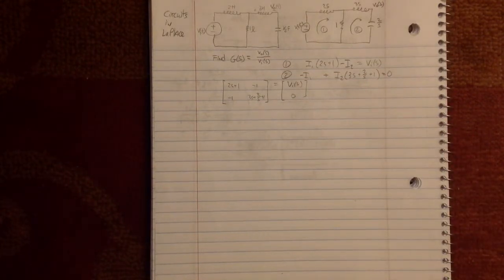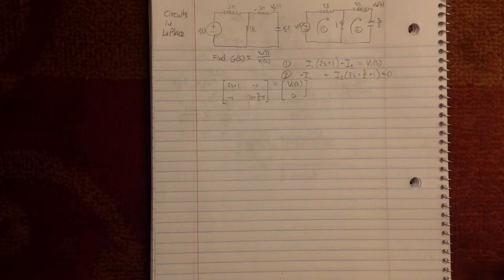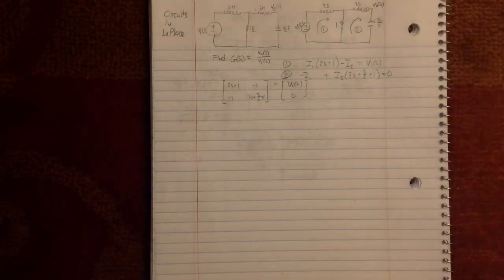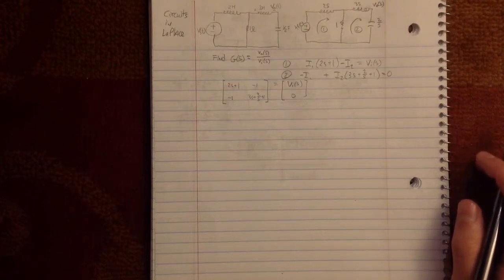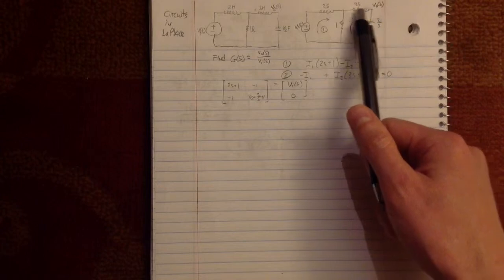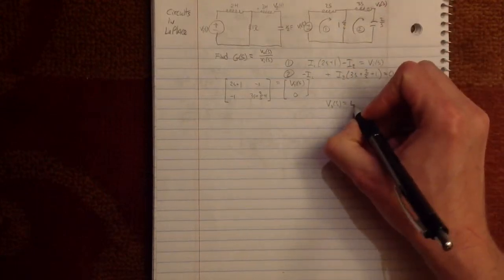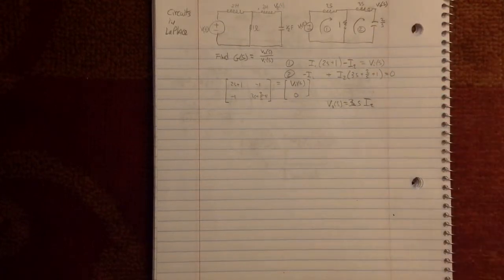Okay, so what you need to do is take an examination of your circuit. So you want this over here for the output. The whole reason for going to the frequency domain is because you can relate capacitance or inductance to current. So by relating it to current, even though one deals with voltage and one deals with current typically, it makes it a bit easier, in quotes, to analyze the circuit. So we can say basically, Vo of s ends up equaling L, the inductance, s times I2. So we know this is 3, so it's going to be 3s I2.